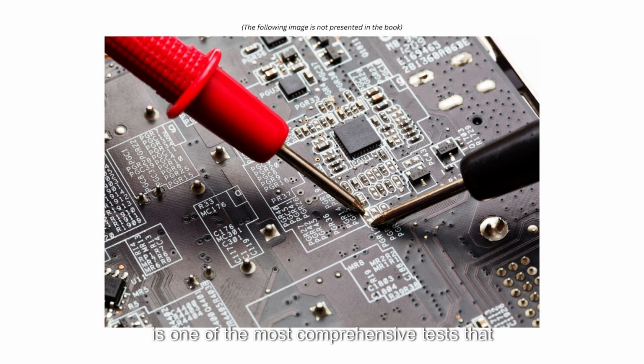Full functional testing is one of the most comprehensive tests that can be performed, but it comes at a higher cost for test equipment, in addition to the process bottleneck it causes in the time it takes to test each board. Functional testing can identify engineering defects as well as manufacturing defects, down to a single test node. This is extremely useful when prototyping a complex board, or when rework is a viable option for the board. In many cases, the development of the test equipment and test program run in parallel with the board design process.